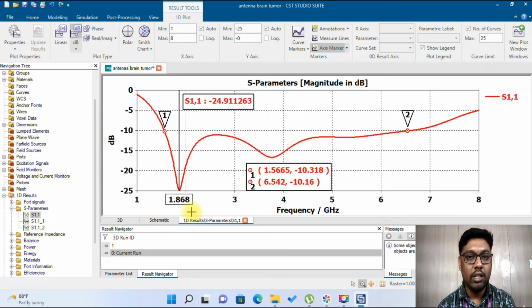The reason behind this is that once we consider these wideband frequencies, the lower band frequencies will have high penetration, and the upper band frequencies will have high resolution. So it depends upon applications. For example, if you are going to apply any image reconstruction algorithm, then you need to focus on the higher band frequencies, which have high resolution capability. But if you are simply analyzing the S11, then you need to get the response from the inner part of the tissues.